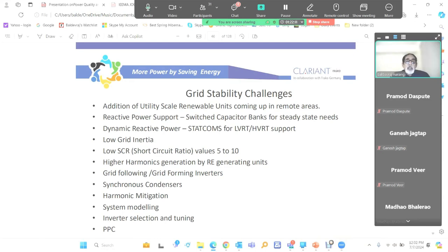Single phase loads generate third harmonic. But in renewable plants, we have harmonics in the range of maybe 23rd, 37th, 49th, and so on. And these harmonics cannot be controlled by active filters, they cannot be controlled by STATCOM, and they cannot be controlled by standard passive filters, LC tuned filters, or detuned filters.